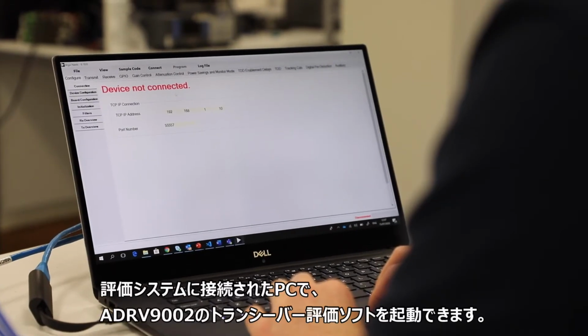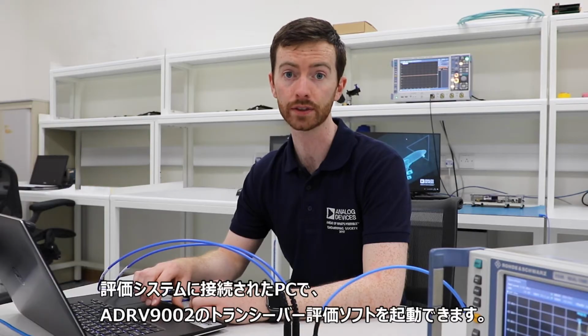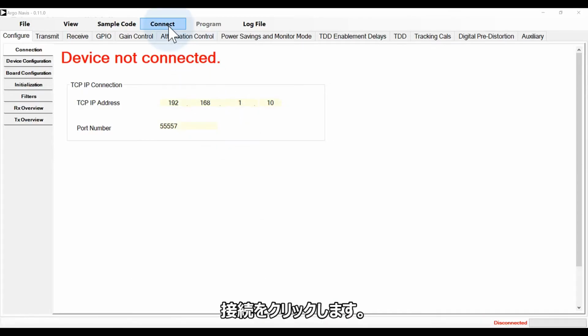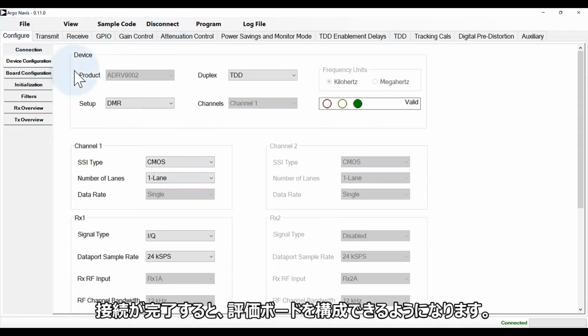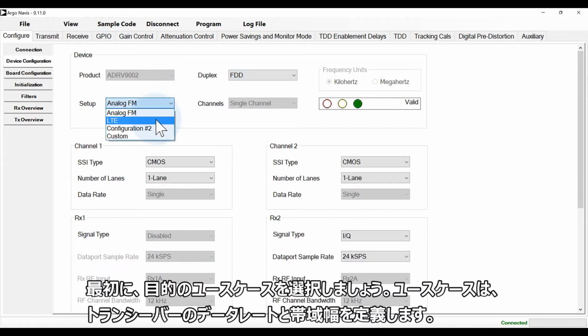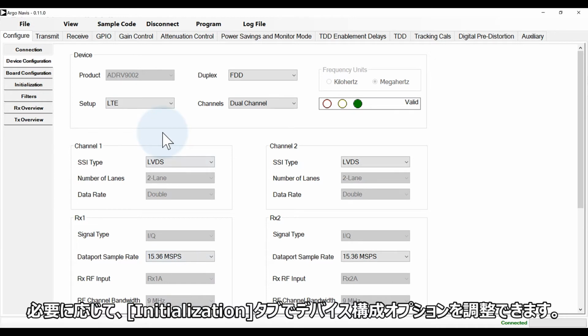On the PC connected to the evaluation system, we can start the transceiver evaluation software for the ADRV9002. We can now click Connect. Once the connection is made, we can now configure the evaluation board. First, let's select the desired use case. The use case defines the data rates and bandwidths for the transceiver. If desired, we can adjust the device configuration options in the Initialization tab.